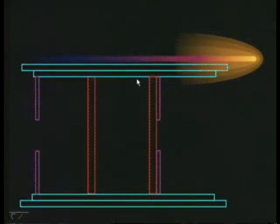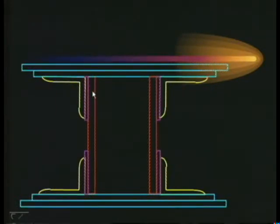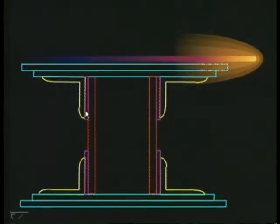Look at this section. You have 2 web plates here. One web plate here, another web plate here, 2 flange plates, 4 angles. So why do you need 2 web plates here? Web plates take the shear, is it not? So when the shear force is more, then you need more area of the web plate. In such a case you can go in for 2 web plates. In such a case it is called a box girder.